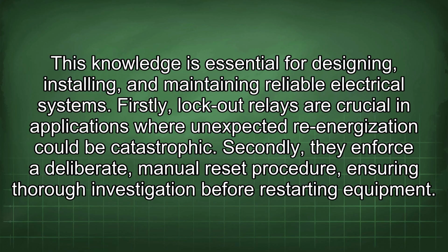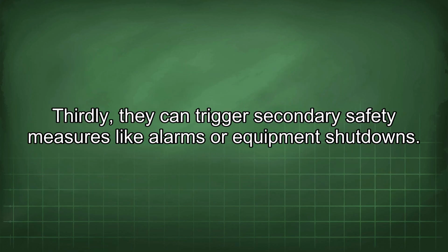Firstly, lockout relays are crucial in applications where unexpected re-energization could be catastrophic. Secondly, they enforce a deliberate manual reset procedure, ensuring thorough investigation before restarting equipment. Thirdly, they can trigger secondary safety measures like alarms or equipment shutdowns.